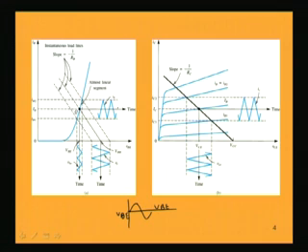Now, the base voltage is increasing, VBE is increasing, base current is increasing, and correspondingly there will be a collector current increment, because now the AC component, AC current small i small c, will be added up with capital I capital C, and small i small c is nothing but beta times small i small b. So, this collector current will also increase. Similarly, when the base current decreases, collector current will decrease. So, we get this increasing and decreasing collector current across the collector to emitter voltage.